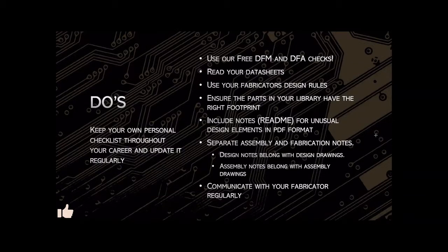One thing I do see a lot that causes a lot of confusion or missed notes on our side is that the customer would put assembly notes inside the Gerbers or in the fabrication drawing. We don't actually look at fabrication drawings, so if you have assembly notes, please make sure they are in an assembly drawing so that we can review all of those and capture those on the assembly side.